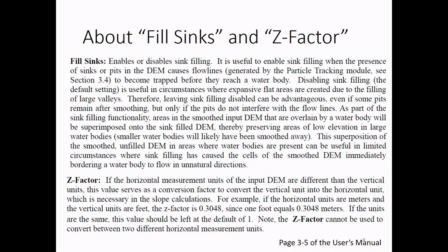But when we use this particle tracking, we cannot. Sometimes the water particle is trapped in the sink, so we have to fill the sink so that the water particle can move out. Most of the time you don't need it, except in Florida where it's pretty flat.